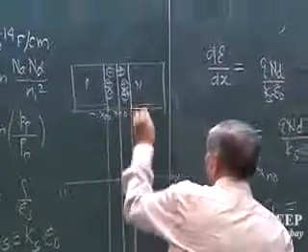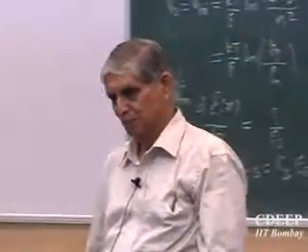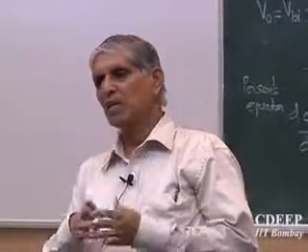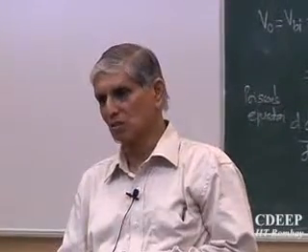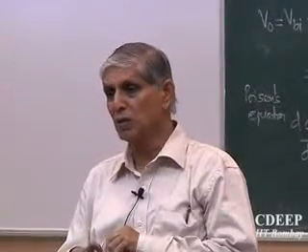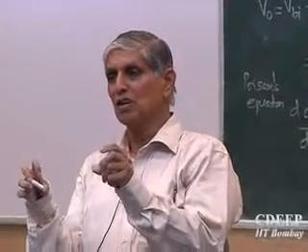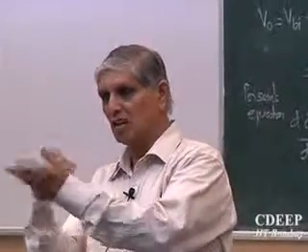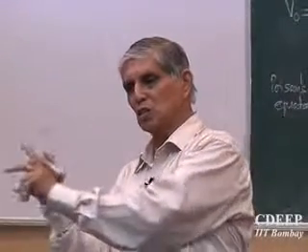See, to the right of xno there are no space charges, so N_D and N_A are 0. P and N type in thermal equilibrium; they will have to balance. There is no free space charge there, only holes and electrons could be there. But they must be equal because there is no current going through. The N current must be balanced by the P current, so the net current is 0. So the drift current is always 0 on the right.